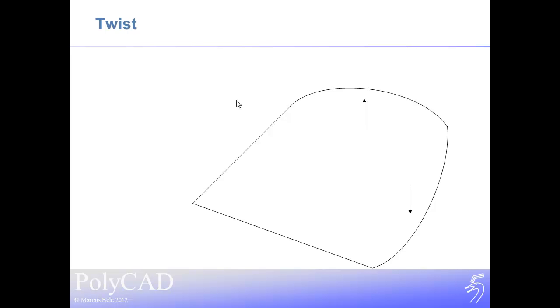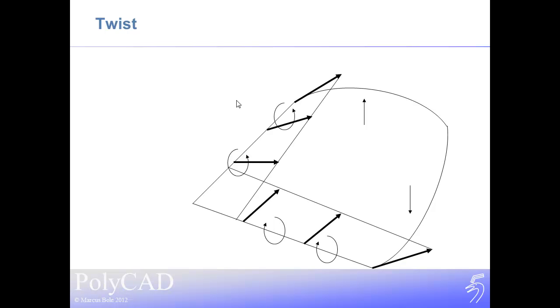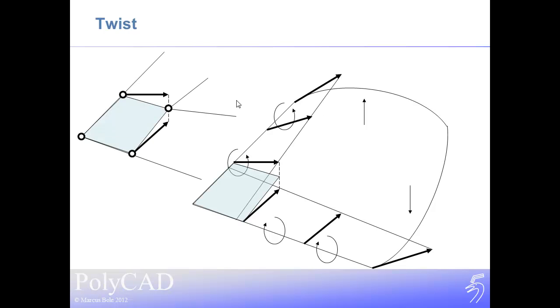So if we now look at our surface tangents along the two straight edges, we see that for the left edge we're going to rotate that surface tangent in an anti-clockwise manner, and that starts to rotate upwards. And for the other lower edge, we will rotate that one clockwise, and that surface tangent will start to bend downwards. Now in the left hand corner we see that the tangents are now going in completely different directions. We have quite a large discrepancy from our original plane for where that control point needs to be located. Because of this conflict, we have only one particular position where we can do it, which is pretty much to put it at the average position of those two vectors. This means that the surface doesn't constrain itself to the shape that we had originally wanted.